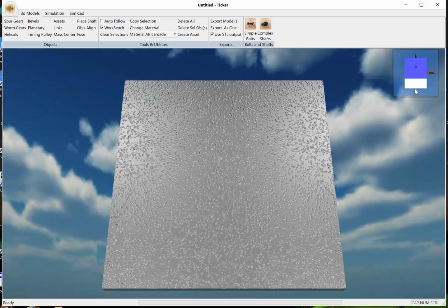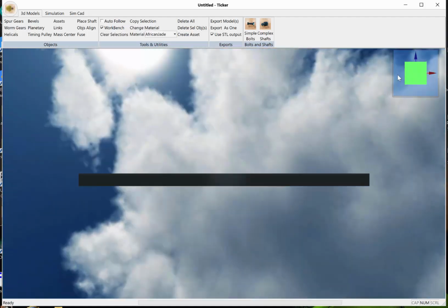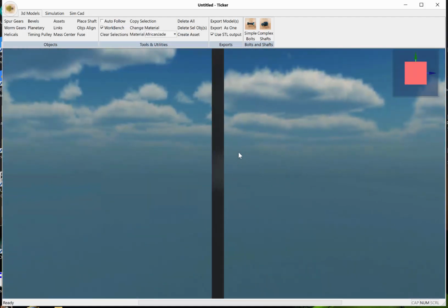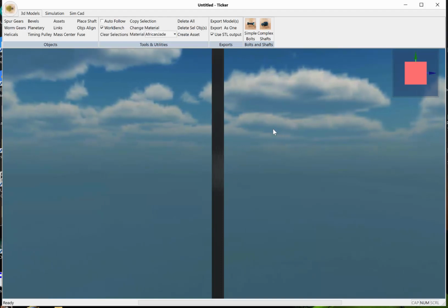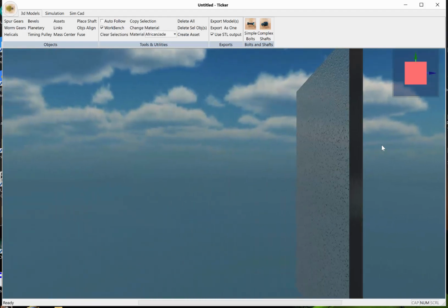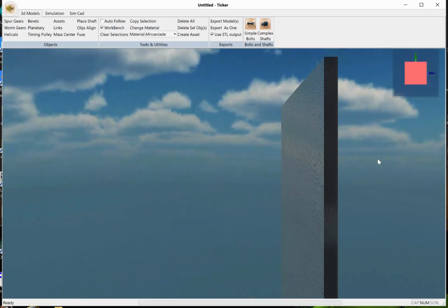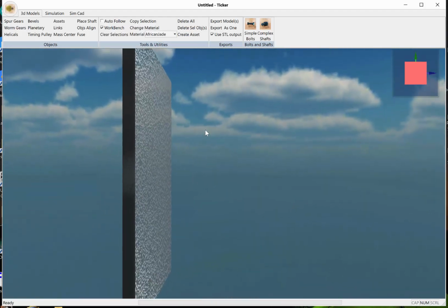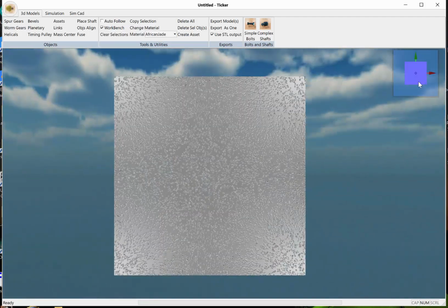If you click on any side of the model placer, it will rotate to show you the device from that angle. Remember that pressing the Shift key and moving your mouse allows you to pan, and you can now pan in any of the axes. It doesn't care. You can rotate around at will and set yourself up with the axis that you wish to work with.